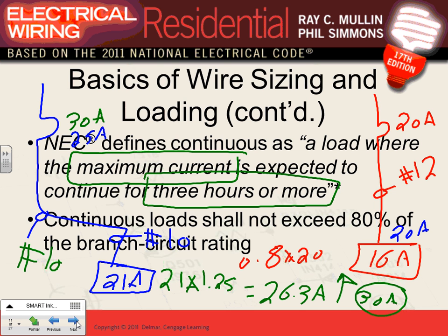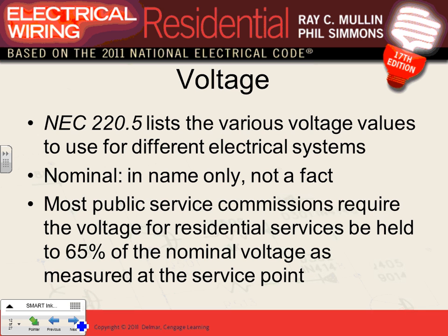Now let me put in a disclaimer. Remember, I'm an engineer. 99% of the time, the loads that we design for hospitals and all these buildings are considered continuous loads, and we use the 1.25 all the time for safety. Okay, so that's your continuous load.